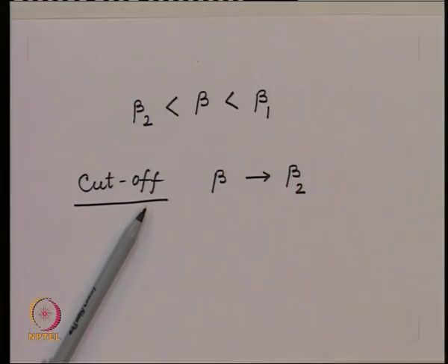So essentially the limit of beta 2 and beta 1 is telling us that the energy is there in these two regions, and because the energy outside the core has a tendency to travel with phase constant beta 2, and energy in the core has a tendency to travel with phase constant beta 1, there has to be a mutual agreement so that they can travel with a phase constant which lies between these two limits.